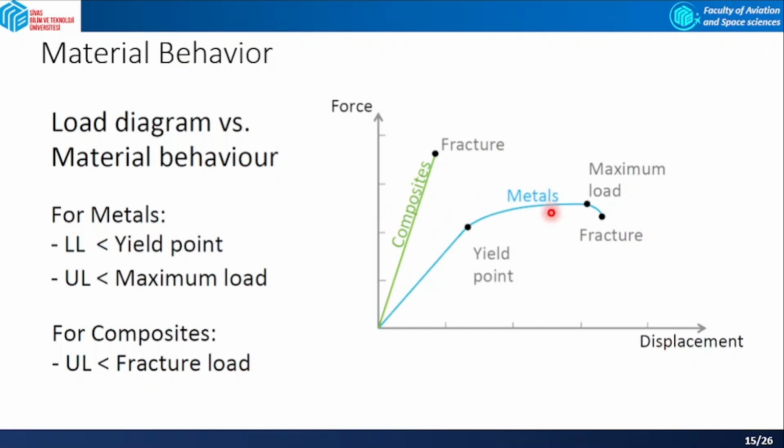Below the yield stress, you see this blue linear part. Below this is linear, and the material exhibits elastic behavior, as I said. So all the deformations will be reversible. And beyond the yield point, the material undergoes plastic deformation. Plastic means a permanent or irreversible change.